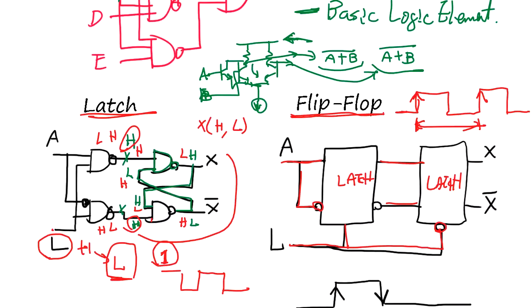So what happens is, say when this goes high, right, then this guy accepts the data here, maybe high and low, right? And when it goes low, then this guy accepts this data here, and this guy starts accepting the new data from A. Now while accepting data from A, this guy holds the previous half-cycle data here.